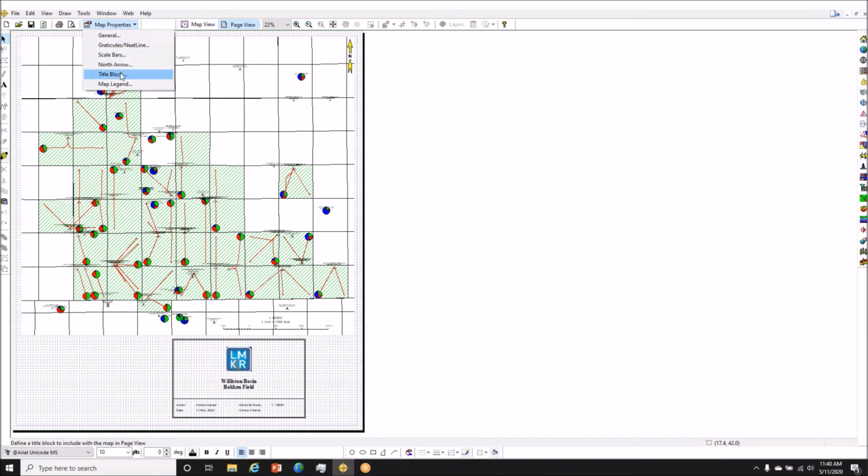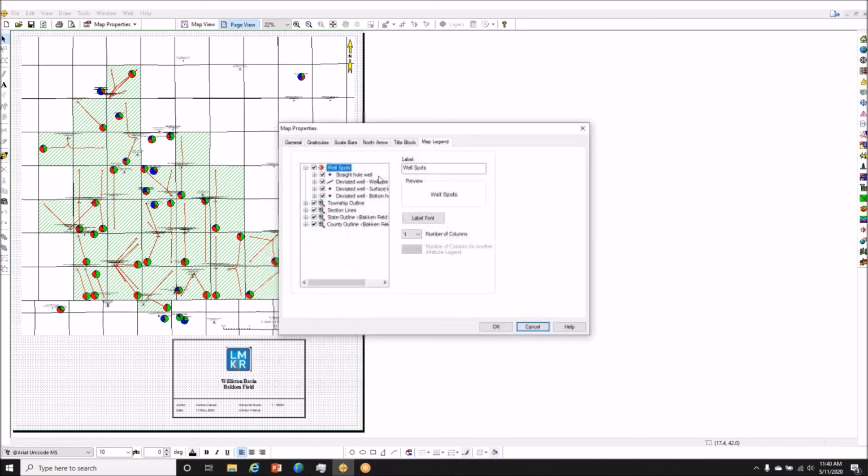And last little bit that I want to include in here, under the map legend option here in GeoAtlas, you can include a map legend from one that's kind of pre-built through the program here. You just choose the entities that you want to include in the map legend. However, you don't get a lot of control with that or a lot of customization options. So what you can do is you can actually create a map legend outside of the program as a metafile.